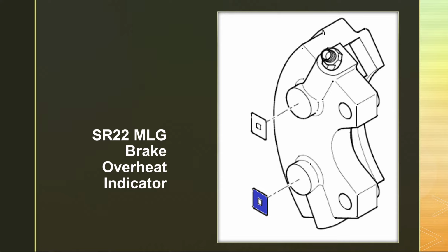They have a very bad habit of overheating the brakes, because specifically the right brake on most of the aircraft that you'll see, because students will drag the right brake to keep the aircraft from going off towards the left because of our left turning tendencies. Instead of applying full right rudder and then only using brake if they need to, too many pilots just drag the right brake. And if you got a mile-long taxi, you just drug the brake for a mile and heated up the brakes the entire time.